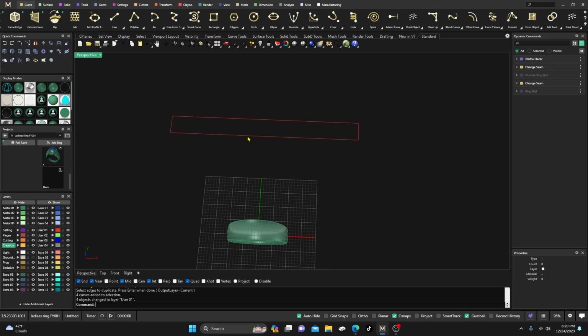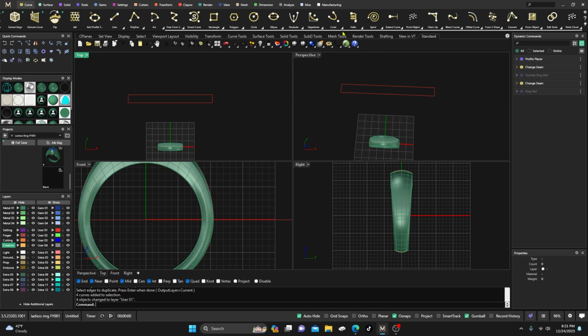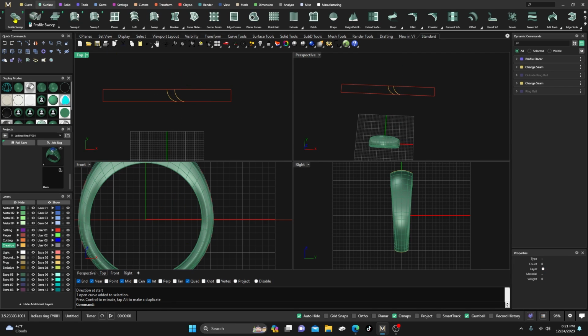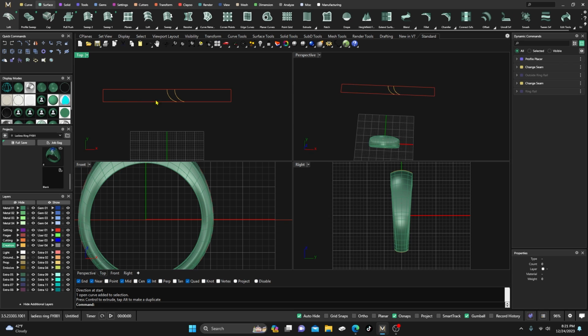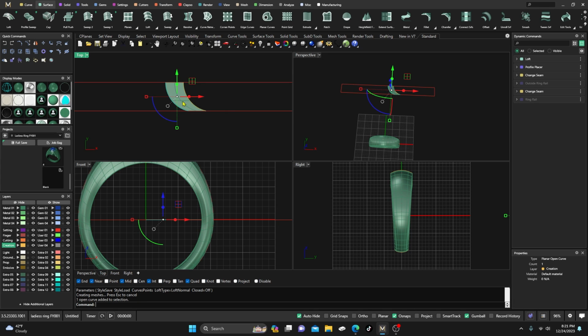Okay, and now when I draw that item out real quick again, center, over here someplace, there, hold down Alt, drag it over, and I'll just do a quick loft here for surface, loft parametric, so I can take this one and hit enter, and then enter. Now if I want to adjust that loft, I can take that curve and move it, and it'll update, right?